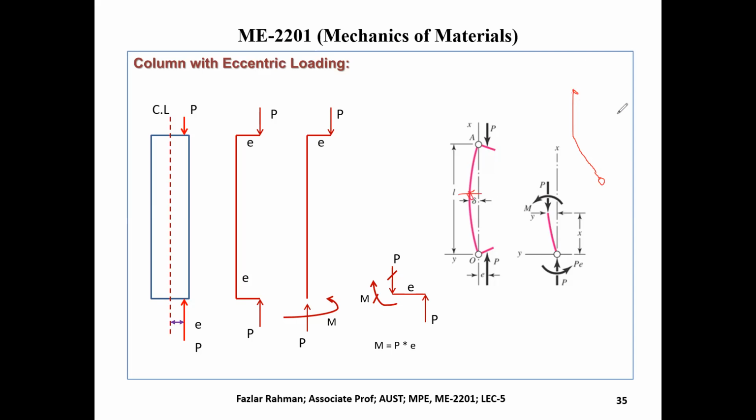Okay, so you see how much load is working at the bottom point. Number one, at the bottom point, the force working is an upward compressive force, P. The other thing working is a bending moment, right over here, M equal to P into E, working anti-clockwise.